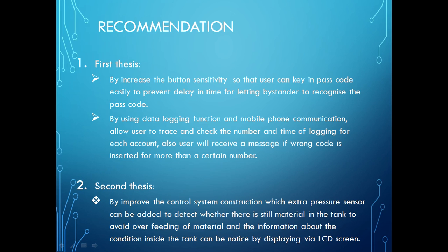For the second one, the recommendations from the thesis are to improve the control system construction, where an extra pressure sensor can be added to detect whether there is still material inside the tank, to avoid overfeeding of material, and the information about the conditions inside the tank can be noticed by displaying it on the LCD screen display.